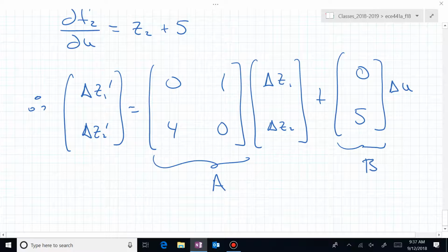How is this system going to naturally behave close to that 0? We're not going to go very far away. We're just interested in the dynamics of these deltas. Delta Z1, delta Z2, and delta U. We only want to venture a little bit away. If we get far enough away, our linearization is not valid. Is that clear? So we're trying to isolate on a small region around the operating point in this case.